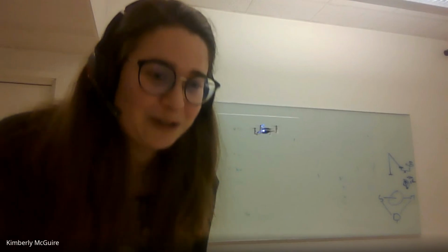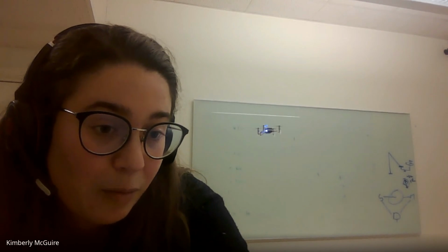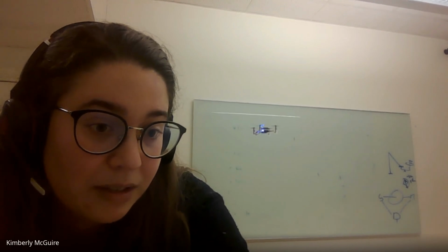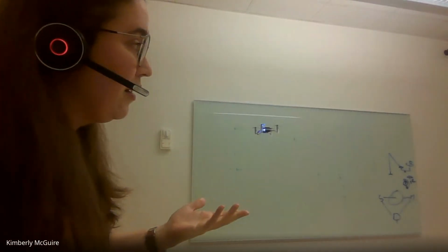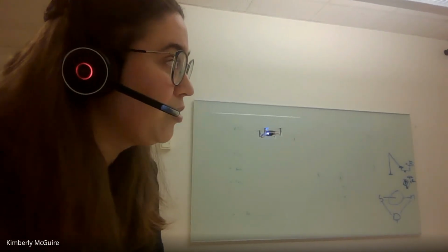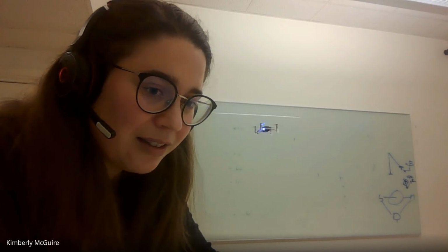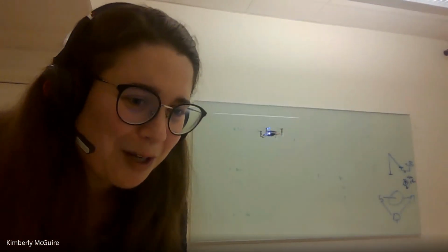I have a question, if you don't mind. Currently, are you using your Python library, or is it using ROS 1 or 2? This is currently using our Python library, but I can do exactly the same thing with the Crazyswarm 2 project as well, because the positioning is pretty much done on board, so the only thing I would give it is a position set point, like I'm doing right now. And one of the backends in that project is also exactly our Python library, so it's not that much of a difference, to be honest. Yeah, because for ROS 1, for now, we are using ROS 1 with the Crazyflies, and it's been quite difficult to take off with mocap.